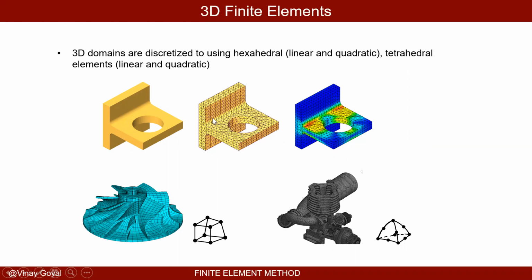Using a two-dimensional model could be okay. For example, here I could have used a two-dimensional element, a shell element, and I will show and discuss shell elements later. But a shell element could be sufficient because of uniform thickness, and it's possible to be able to get there. But if this is very short compared to a thickness, then you start to want to use the three-dimensional elements. They're more effective.